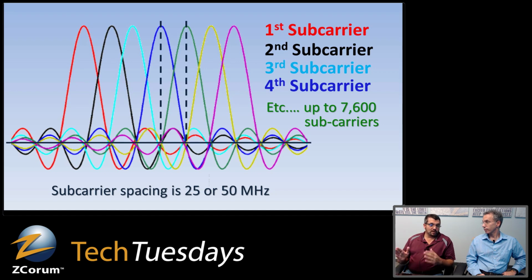So they're actually overlapping, but where one signal's bottom is, the other one's peaked. Right. So they can overlap, and you don't need all these guard bands that you would have in traditional SC-QAMs. Right. So if you look at the two center ones there, you see that line coming down. What Pete's describing is you've got your peak on one signal, and then as you trace that down, it's hitting the null of all the other signals. So you have no interference, and you've got all of these little subcarriers overlapping each other.